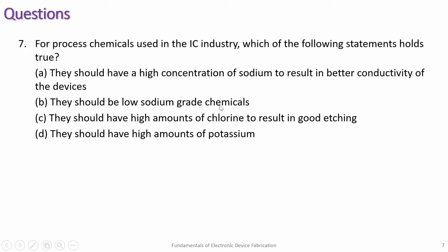Sir, it's actually related to the concentration. Suppose we have a wafer in the nanometer size and we use dopants. Dopants will be used in parts per million and parts per billion, right? So if they have additional metals present, that will give rise to ions. Suppose there is NaCl in your chemical, and it will dissociate into Na plus and Cl minus. These Na ions will start contributing to your conductivity, right? So whatever doping you did will not be of use because dopants will be present in very small concentration and the functionality of the die will be lost. So that is the reason. Is it clear?